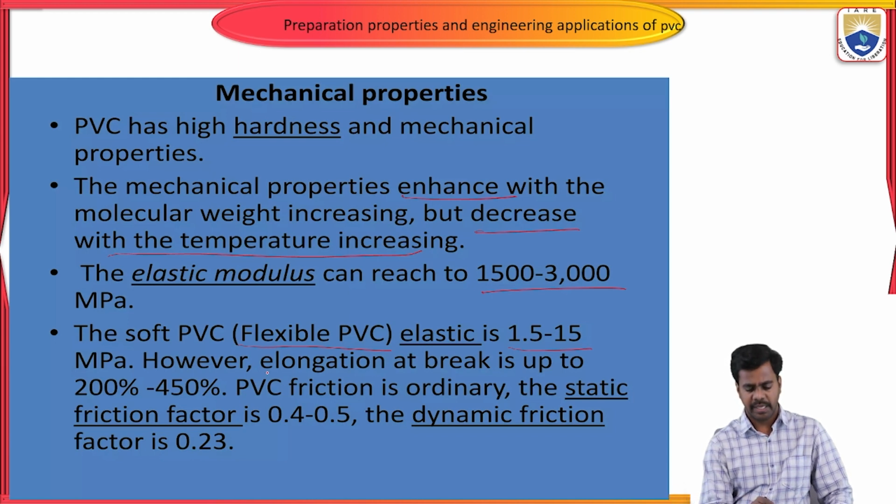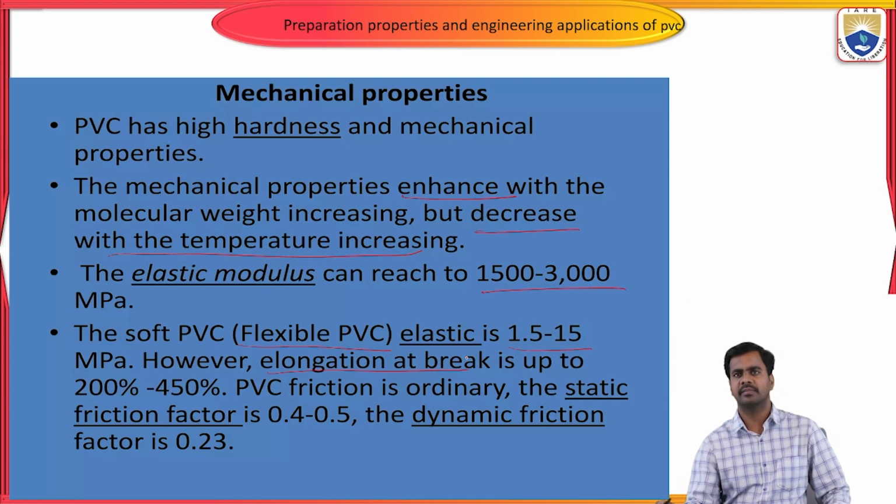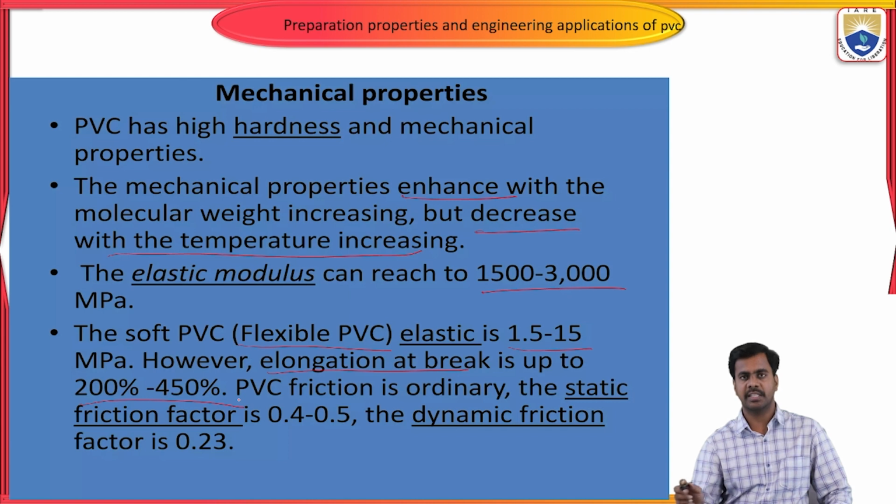However, elongation at break is up to 200 to 450 percent. Friction is ordinary. The static friction factor is 0.14 to 0.5. The dynamic friction factor is 0.23.